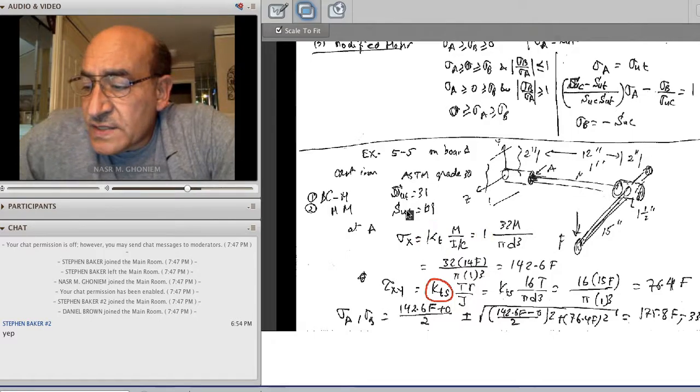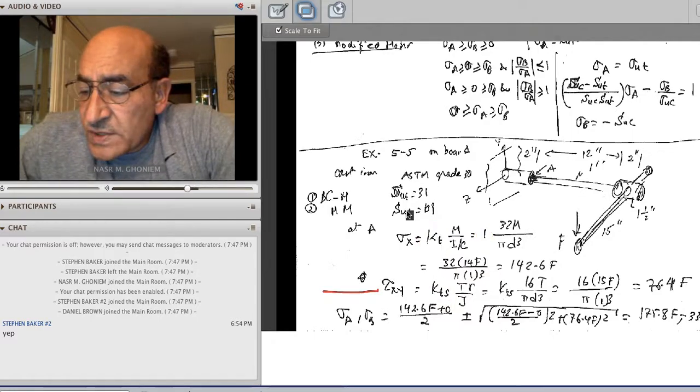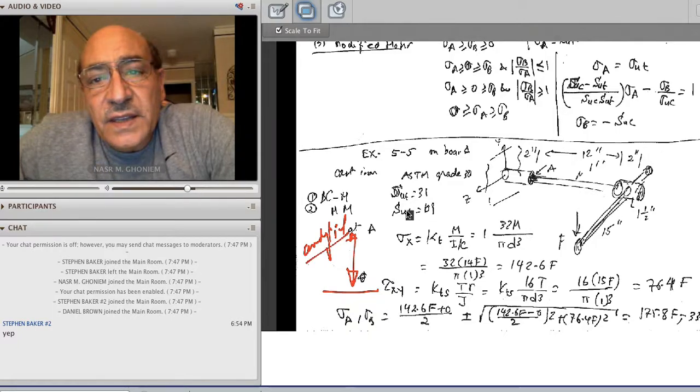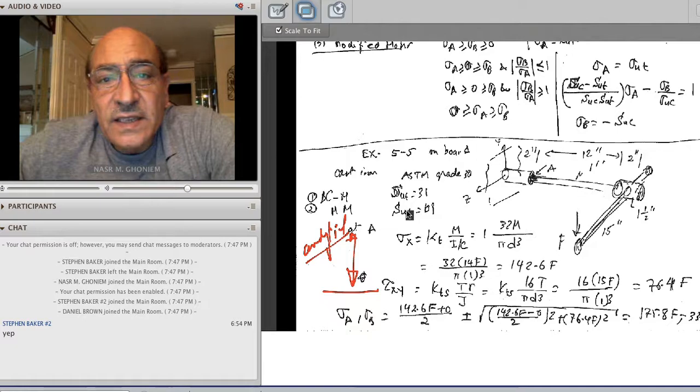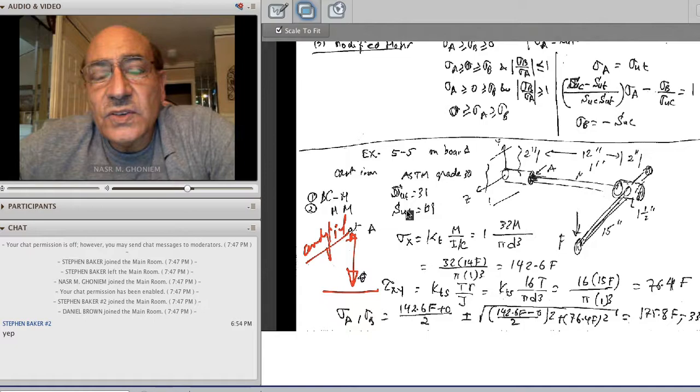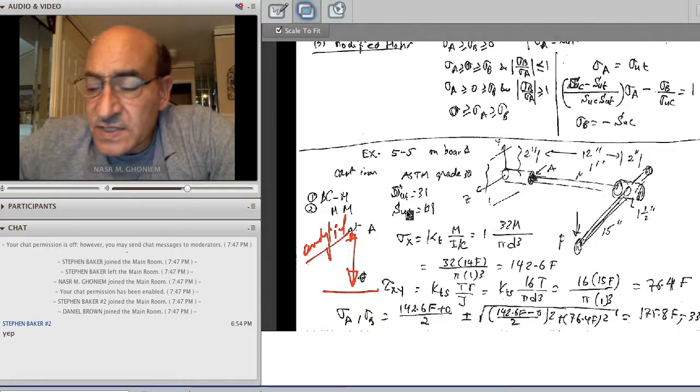As I mentioned, it takes a little time, and up to this point is analytical, right? Because this is why we have developed all of these formulas. In your project, you can get the stress distributions numerically. And in real-life design, this step is the finite element step where you do all meshing and you look at the stress tensor everywhere, and then you determine the point that has highest probability of failure to be the one that has high maximum stresses, for example.